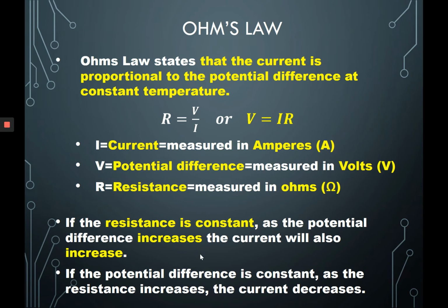So your standard light bulb, technically this doesn't apply. But like many things in physics, we assume an ideal world where things like this are not actually happening. V equals IR is assuming that the resistance is staying constant. A regular filament lamp light bulb or even your LEDs can get warm, and so they don't truly obey this law, but it is the best prediction of what these values would be.